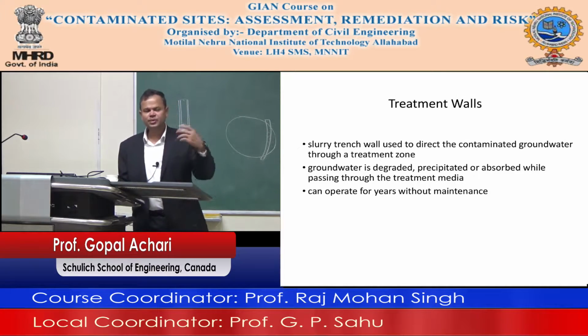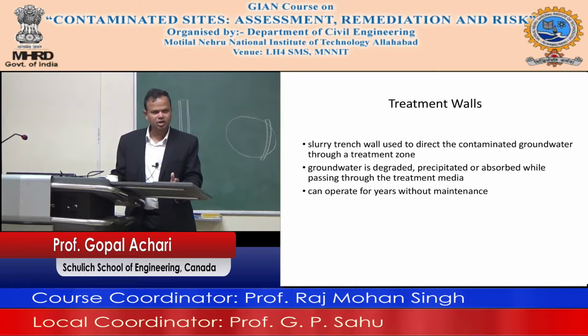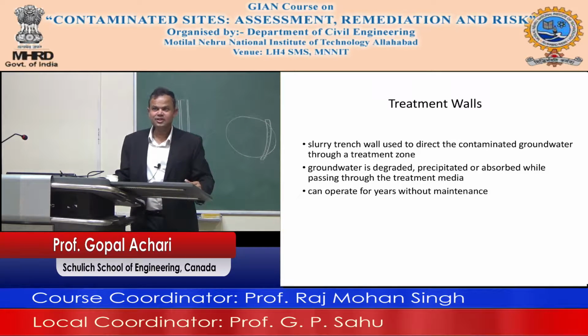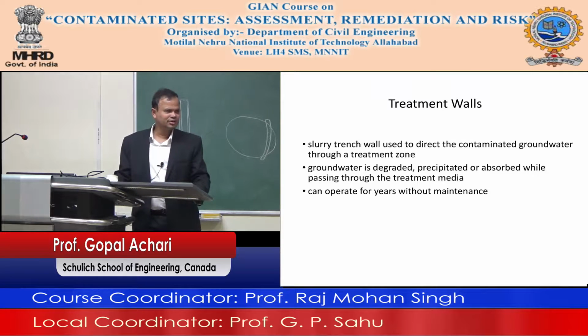If you are doing a computer simulation of a contaminant transport model for a particular site, it might be worth your time to see what treatment I can do so that my plume can shrink, by putting different scenarios around it. The amount of time you spend developing a flow model, a transport model, and calibrating and verifying the model, it's not a whole lot more time to see how I can treat it.